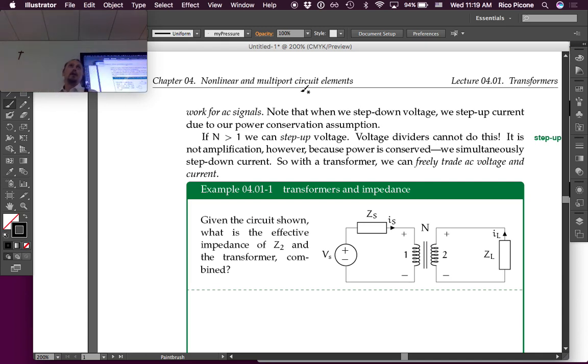And this is actually used to our benefit at times, because we can use that to isolate two circuits from each other. The DC component is completely missing from the interaction. So you can decouple the DC values of a circuit, which is useful when you want to isolate two circuits from each other in terms of the ground of each circuit.